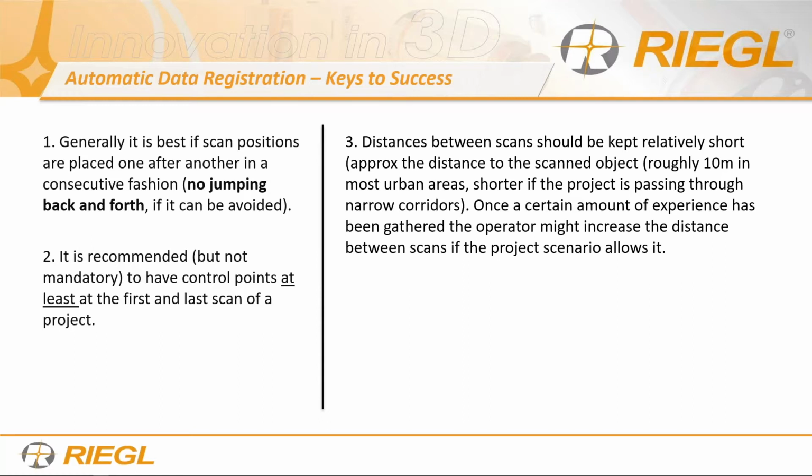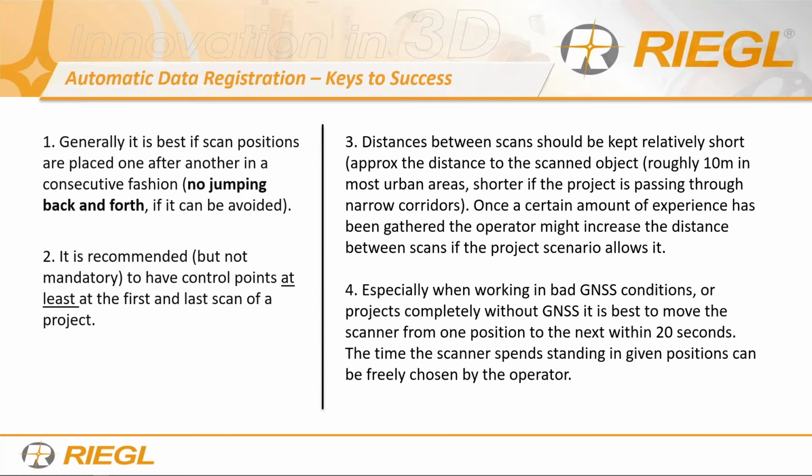Now, if you have it on a vehicle where you have it up 10 to 15 or even 20 feet in the air, now your horizontal surfaces can get much wider, and therefore you can move at a larger distance between each scan position. So be mindful that we need the overlap, right? The overlap is key, basically. That is what we're trying to say here.